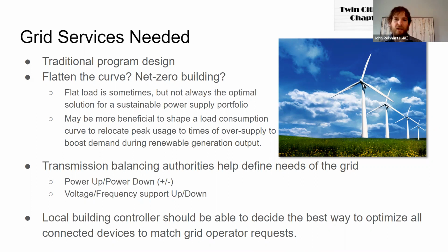Flattening the curve is actually a really interesting concept. And I think that it is sometimes beneficial to maintain and manage that load profile, especially when considering if peak usage at a building is in a congested area of a distribution circuit, and you're worried about overloading the substation, the transformer, the electric lines. You need to maintain and use those power lines and infrastructure as well as you can. So a flat load profile may help prolong and delay any capital upgrades.